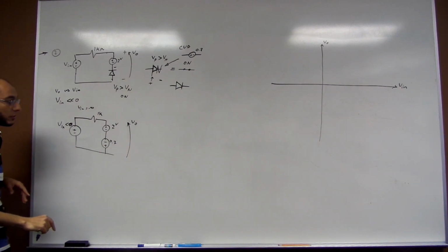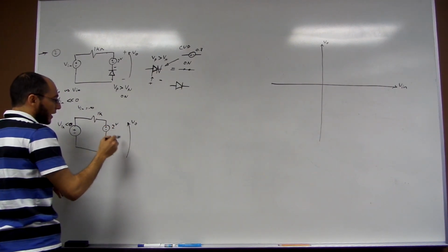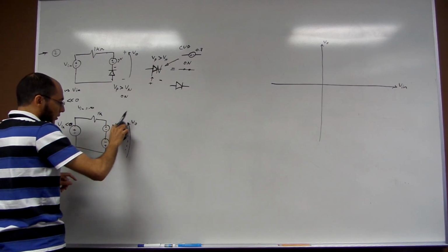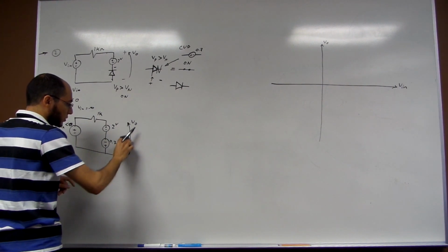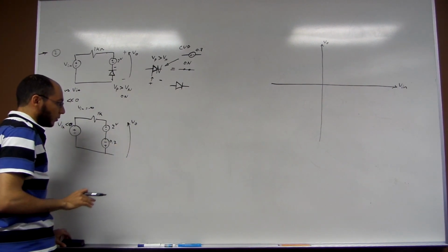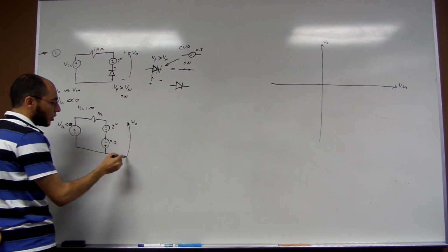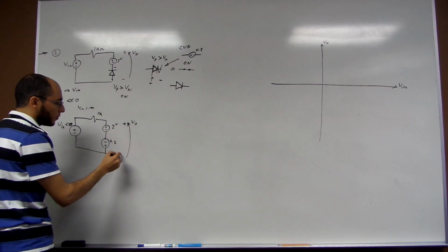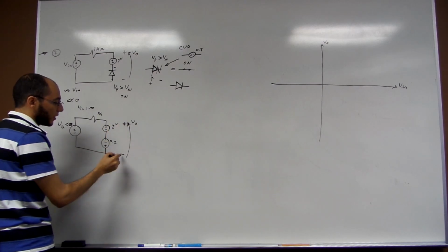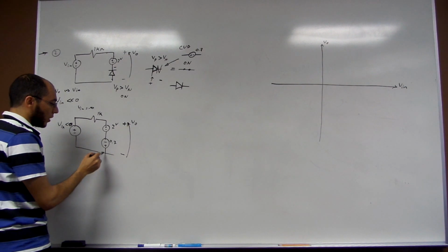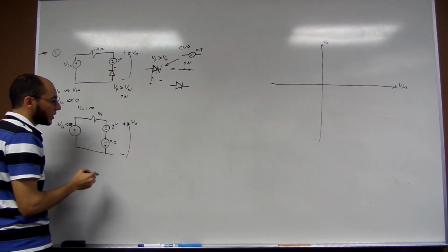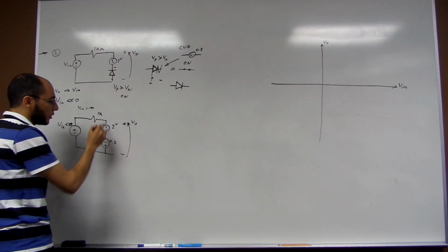How do I calculate the output voltage? Let's do a KVL in this circuit. Well, that might confuse you. I'm going to say the systematic way and then say the KVL way. So what is the voltage of the output? The output starts from down to top, from the negative to the positive. So I'm going to look at this node and move forward till the top and see what is the value of the voltage at that node compared to this node.